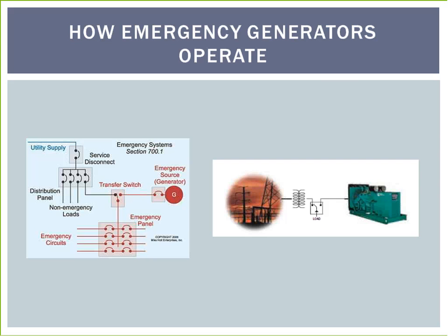These latter systems do not produce polluting gases, thereby allowing the placement to be done within the building. With regular generators, an automatic transfer switch is used to connect emergency power. One side is connected to both the normal power feed and the emergency power feed, and the other side is connected to the load designated as emergency.